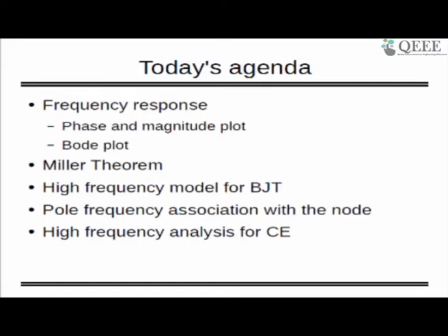Today's agenda: maybe I'll give you a little bit of flavor of what a Bode plot is, the phase and magnitude plot. After learning that, there is a very important theorem, which is important to understand frequency response, or the poles and zeros associated with the BJT or the transistor, which can be understood from Miller theorem.